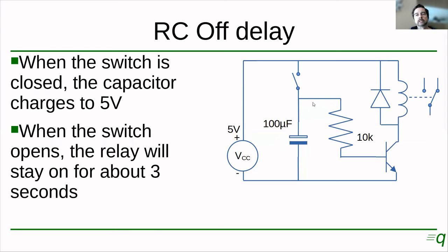At some point, the capacitor is going to be discharged and the relay is going to turn off. So this circuit should keep, and this depends on the transistor and the relay, but this circuit should keep the relay closed for about 3 seconds after you open the switch.